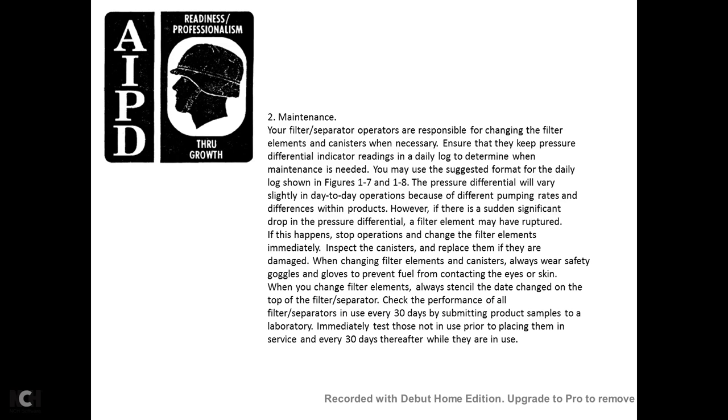Two, maintenance. The filter separator operator is responsible for changing the filter element canisters when necessary. They ensure the master differential indicator reading is kept in the daily log to determine if maintenance is needed. You may also use the suggested format for the daily log shown in figures 1.7 and 1.8. The pressure differential varies slightly with day-to-day operation because of the different pumping rates of different products. However, if there is a sudden significant drop of the pressure differential, the filter element may be ruptured. If this happens, stop the operation and change the filter elements immediately. Inspect the canister and replace them as needed or if damaged.